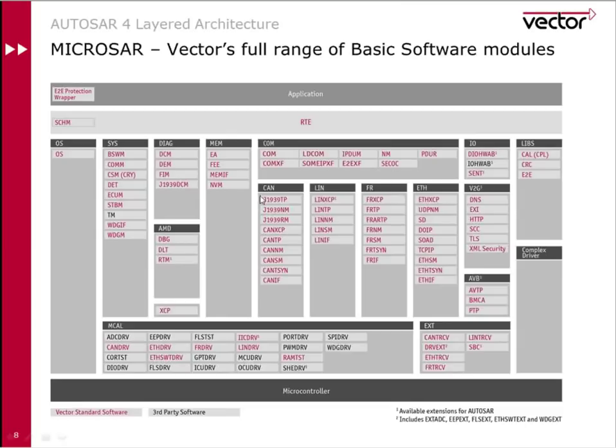Further along the line, we have the diagnostics modules, DCM and DEM, that's Diagnostic Communications and Diagnostic Event Manager, and FIM, Function Inhibition Manager. I don't have time in this webinar to cover every single module within the stack, but hopefully I will give just a brief introduction to the most important modules. Underneath this, we have the AMD modules, and this is for AUTOSAR monitoring and debugging. This part of the software runs above XCP and allows you to view and debug the internal variables of the AUTOSAR stack prior to production.